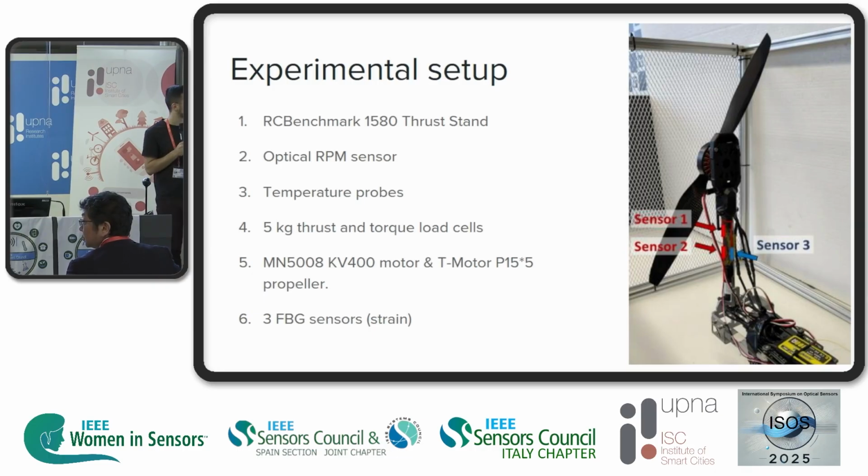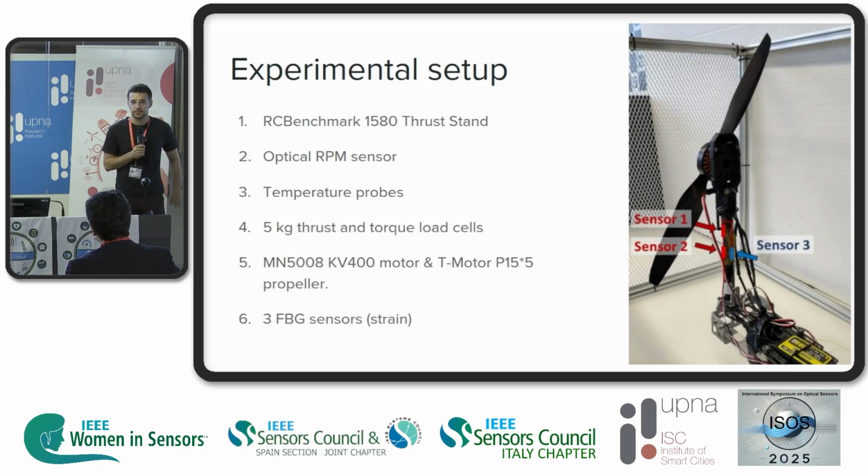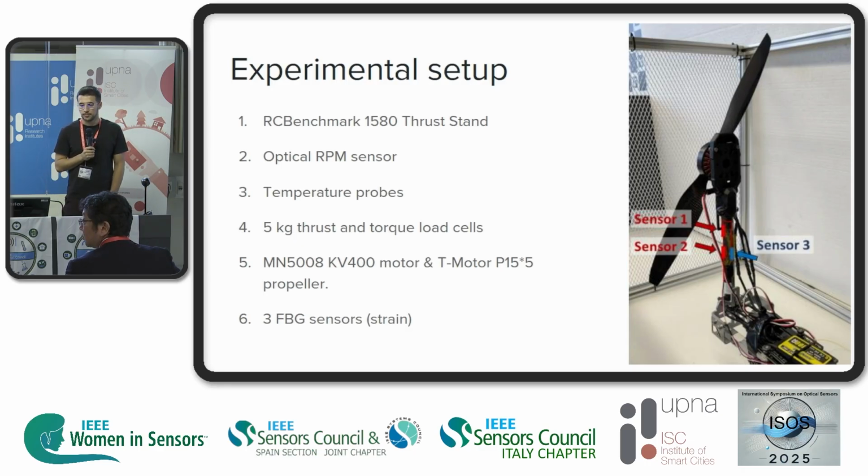That's why we put two sensors, to check how the amplitude was reduced with distance. And on both sides, just to compare, one was working in traction and the other in compression. The results are only for one of the sensors. We could have included all three, and all three gave the same data, because the data is not based on the amplitude or whether it's working in traction or compression, but on the changes in the frequency analysis.